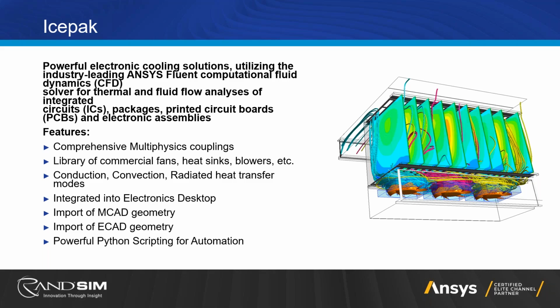We can go in and assign thermal dissipation values. What I'm going to be showing you today is that we can also take electromagnetic simulations done in SIwave and apply those as the excitations for a thermal solve in Icepak. So there's a really nice transition between the two tools, which allows you to get a very exact result for a thermal simulation.